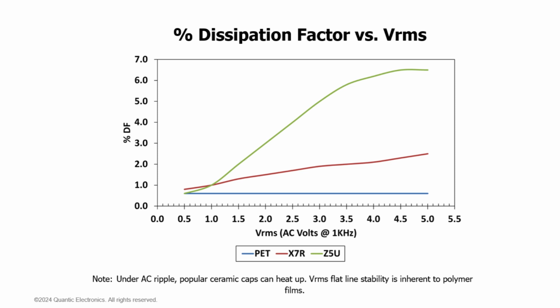One very interesting thing about polyester and most film capacitors is there exists no use-related degradation mechanism with these capacitors. They may age from things like environmental moisture ingress, from crystallization over time or breakdown of the dielectric, but there is no age-related degradation mechanism like there might be with ceramics. So their effective lifetime is extremely long in the field.